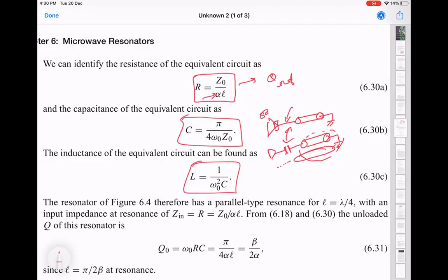For example, if I make a parallel plate capacitor with 100 micron by 100 micron square plate, and I compute the area, I know the dielectric constant, I know the thickness, I can compute the capacitance as A epsilon naught over d. And that will not match what we actually measure in the experiment. These kind of things can be checked using the finite element simulation software. So that includes the finite size effects as well.